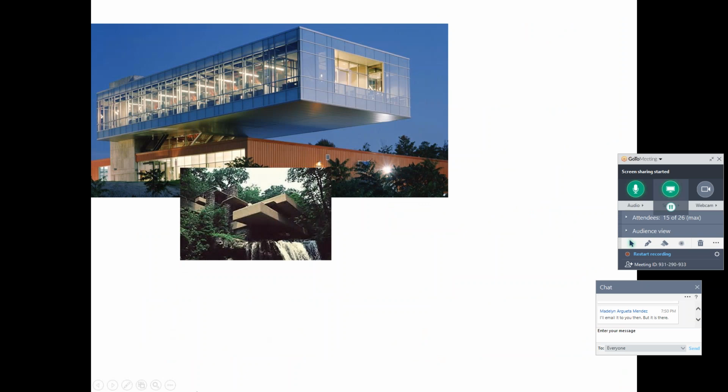Here, and I kind of left it uncompleted because I was working on these slides today and I wanted to add in some narrative, but we're looking at cantilevered buildings and it looks really unbalanced and like it's about to fall off, but the way that a cantilever functions, it's just fine. And some of these buildings, they have used some very complex math to balance that and a balance of materials. So at the back we see a supporting masonry item, which would most likely be concrete masonry units, fully filled, this full thickness, which would help balance out the weight of the cantilevering glass portion of it that's on the grid system of steel.